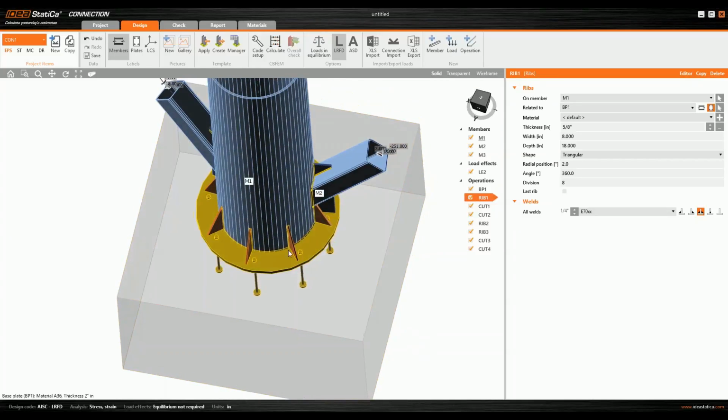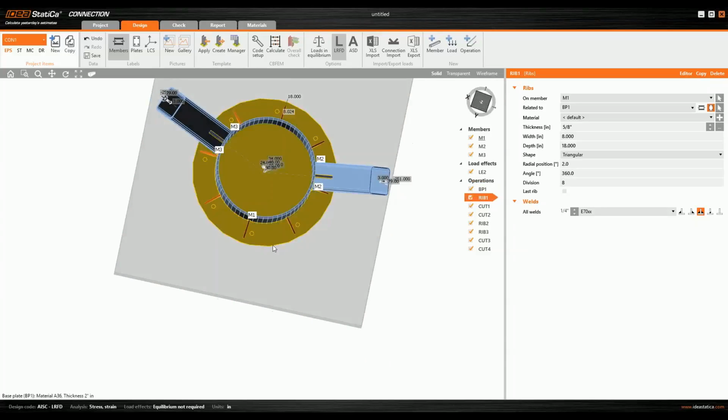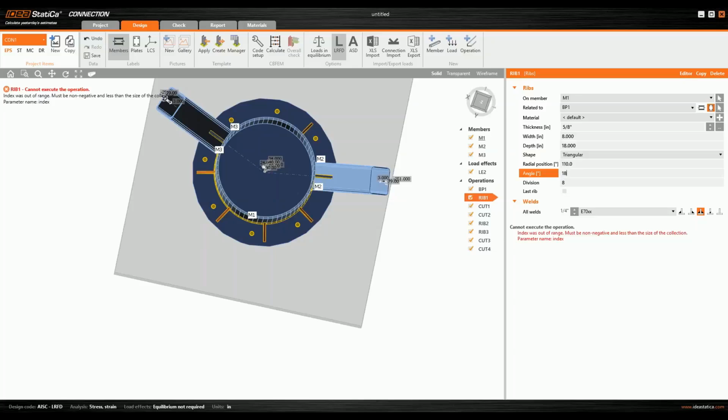We could use a trick, and the trick will be that we divide the rib operation into two. So for the first one, I will modify the, let's say, bottom part, or the bottom half from this side of view of the stiffeners. So I will change here the position like this and change the number.